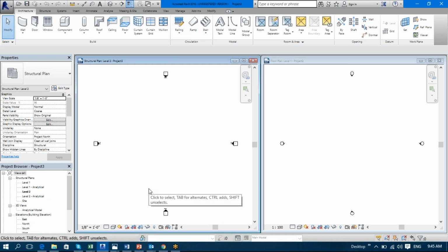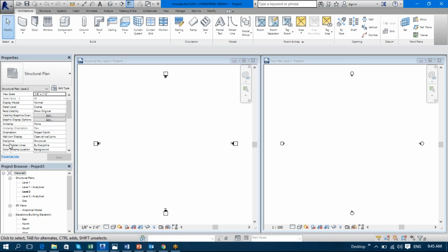When you see an architectural floor plan, you won't find the structural plan in it. And by default, if you go here, in the discipline, it would be written out as structural. So whatever structural elements you create will be visible, but whatever doors and windows you create will not be visible in the structural template. There are ways for us to see those things, but by default we get these settings. Now, my intention was to tell you the difference between an imperial and a metric template.